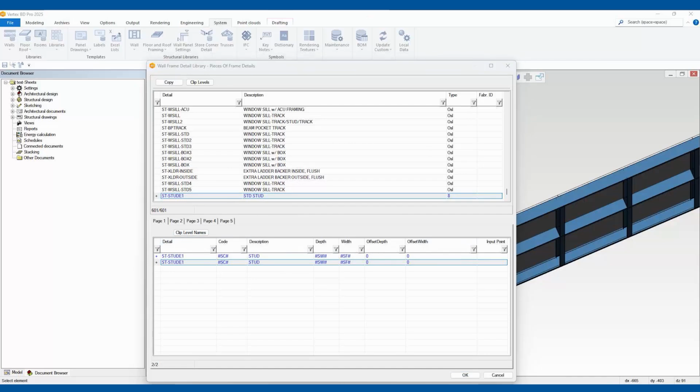So what we're going to do is come over here to offset width. Now I've just got this formula saved off to the side, and we're going to add that in. So what that's saying is it's just stud flange divided by 2, and then KF off is a tolerance between them, which could be set in material specs.